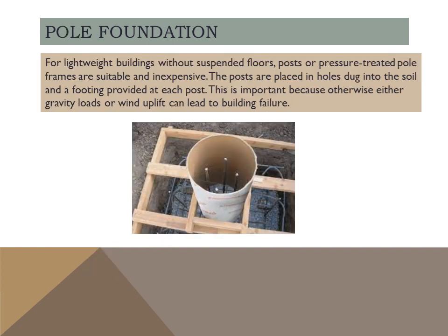Pole foundation. For lightweight buildings without suspended floors, post or pressure treated pole frames are suitable and inexpensive. The posts are placed in holes dug into the soil and a footing is provided at each post. This is important because otherwise either gravity loads or wind uplift can lead to building failure.